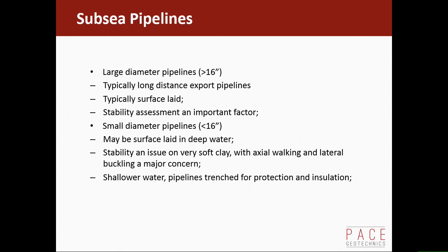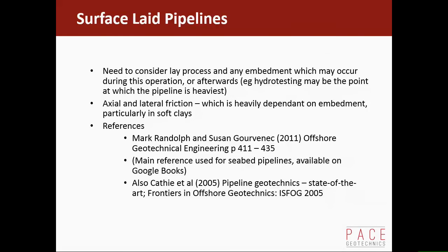And as I said, shallower water pipelines tend to be trenched for insulation and protection. So starting with surface laid pipelines, we need to consider the lay process and how that might affect the embedment which occurs during the actual pipe lay. Axial and lateral friction, which again, particularly in soft clays, is heavily dependent on the depth of embedment which is experienced. And those are some references.